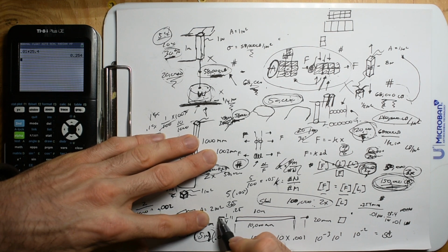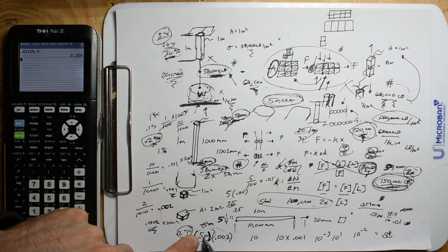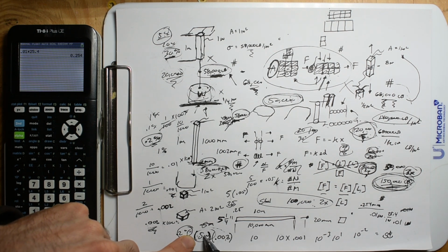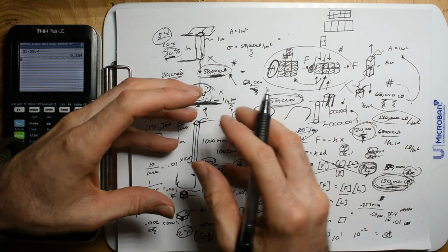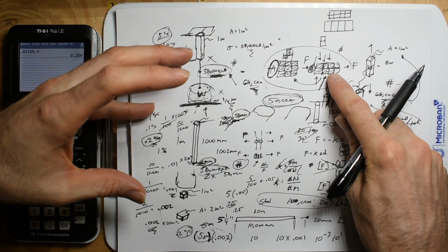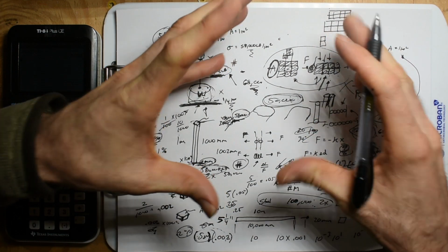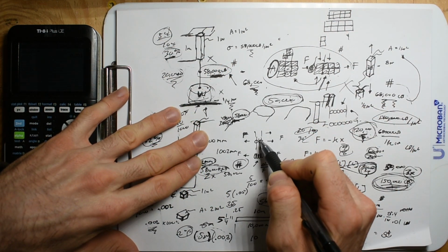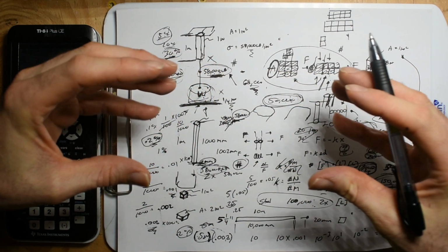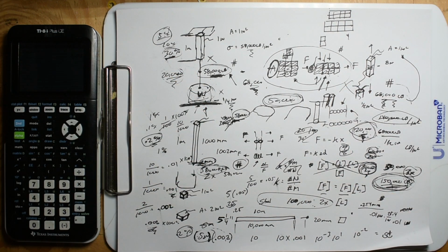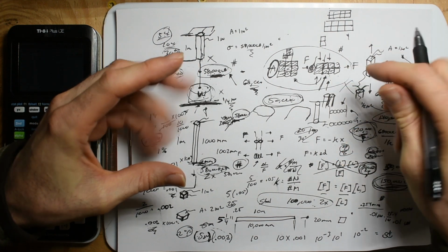What's going to happen when I stretch it to 5 1/4 and then back off the nuts? Is it going to go back to 5 inches? No. Is it going to go back even close to 5 inches? No. All the molecules changed locations, and you're still applying that tension. But when you back off the tension, the molecules just go back to their elastic state. So if you plastically deform it, it's like forging it. You've basically changed it into a new chunk of steel, made a new shape or tool out of your steel, and you're still holding that force.